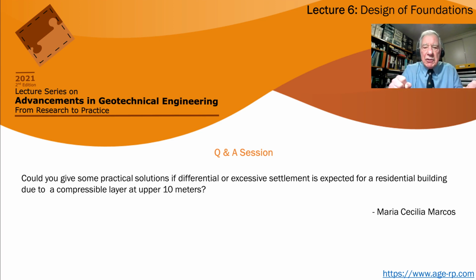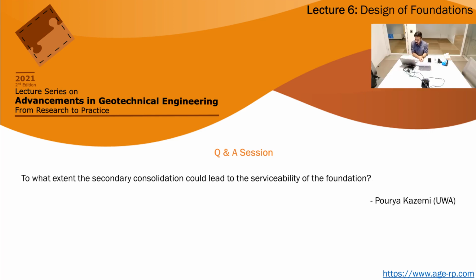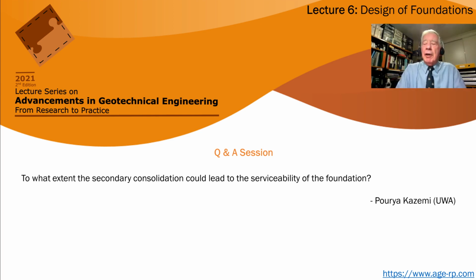So at the very least, if you're using a shallow foundation, use a raft or a series of waffle pod type of substructure. To what extent could secondary consolidation impact the serviceability of the foundation? Yeah, that's a good question.